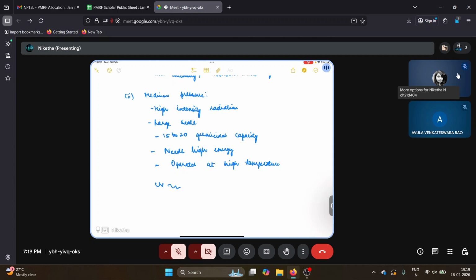That is why we have to keep the UV lamp in close contact with the water that needs to be disinfected. Ideally, it will be like a tube with a UV lamp inside, which will generate UV radiation. Water will be passing through, and in between there is the UV lamp.